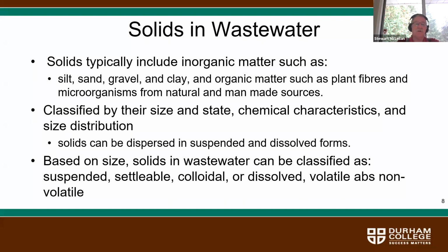The suspended solids are generally speaking easier to remove from water. You can pass water through various filtration systems, which will remove those suspended solids. But the dissolved solids can be a bit harder to remove, because they usually involve some type of reaction to convert these to suspended solids so that they can then be removed.